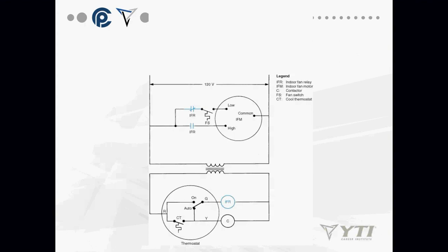Okay, this is an example of a transformer in a circuit. We have our transformer in the center here. We know what the voltage is because someone labeled the primary voltage. And because it's an air conditioning circuit with a thermostat and everything else like that, I could say that it's a 24 volt down here. Now, on your schematics, I really want you to label the voltages, because that's one of our standards, so you'll want to label 24 volts. This is a basic cooling circuit.